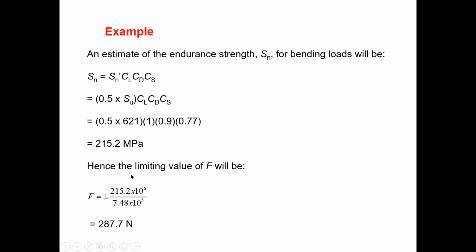So then we can calculate the load. We do not deal with the stresses now. We will get the answers for the load. So don't worry about the stresses then. So we can find out the load value. But in here, you will not introduce Kf. Due to that, the Goodman line Sn value will be this value. So in here, Kf equals 1.